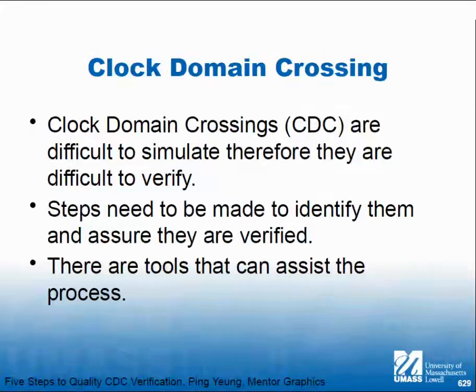How do I know that if I don't get those errors that I've designed my clock domain crossings correctly? You don't. Also, if I have those two clocks and they're different, I can't smoothly change them relative to each other. I can only discretely change them. So it's going to be one point where they work, one point where they don't work. The most important thing in clock domain crossings, in asynchronous design, is that indeterminate case.